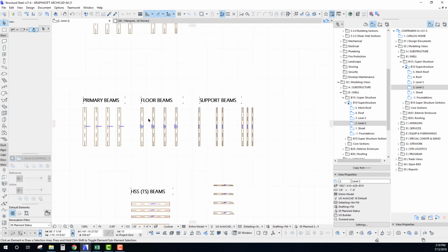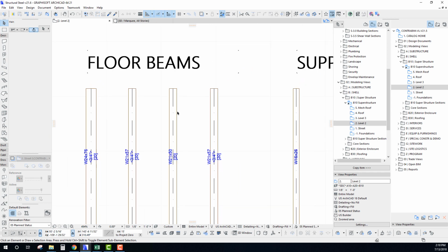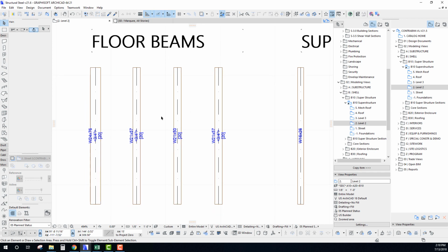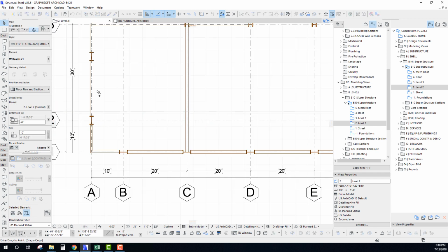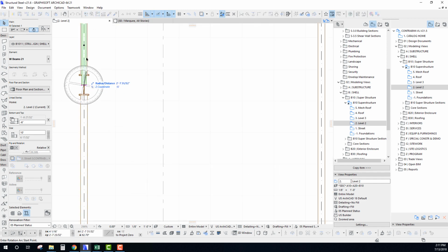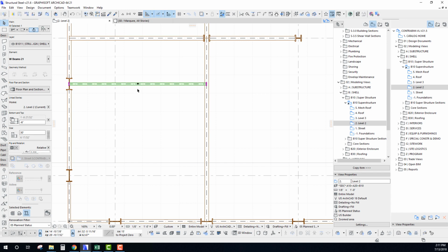So okay, our floor beams, really I think probably like a W21 by, I don't know, 57 or 76. That's probably the right range that we want to be for these intermediate beams. So let's go ahead, and I'm just going to do a 50 in this case. And I'm actually going to just snap this one from right there. And let's kind of check our spacing here.